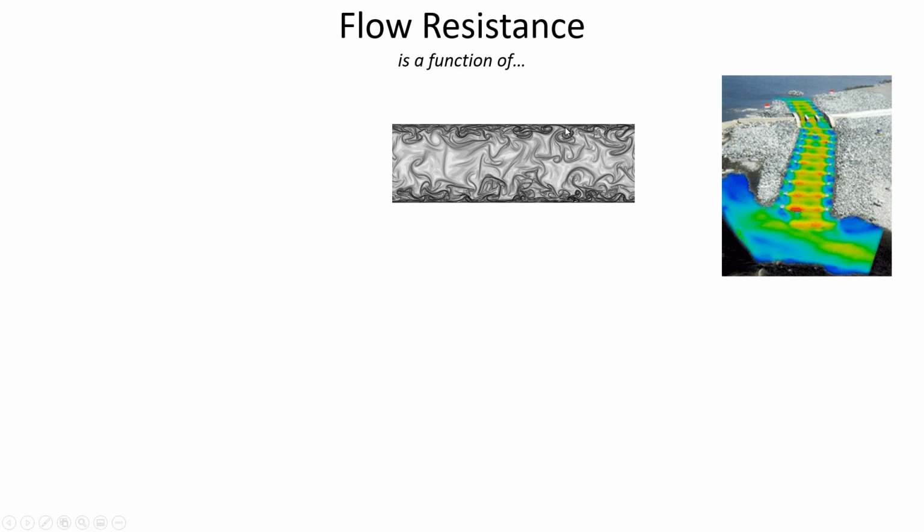And the same thing is true in the pipe. This is just an illustration of water flowing through a pipe, where you can see at the edges the velocities are less, noted by the darker shades, and it's lighter shades in the middle. And it's turbulent flow. This is not laminar conditions. This is turbulent, where there's a lot of cross-current flows and swirls and eddies and turbulence, but there's more turbulence at the edge and less of a forward velocity because of that.